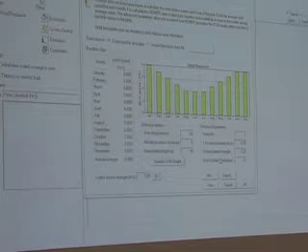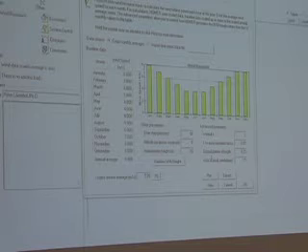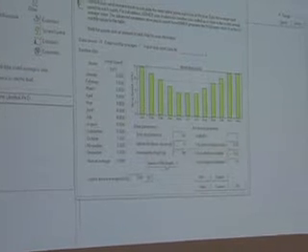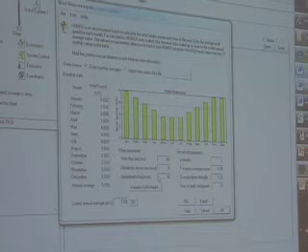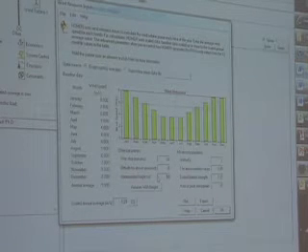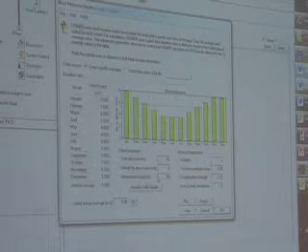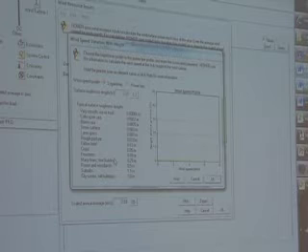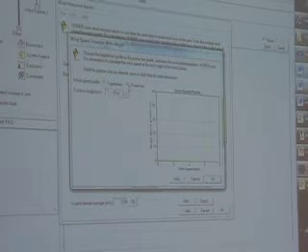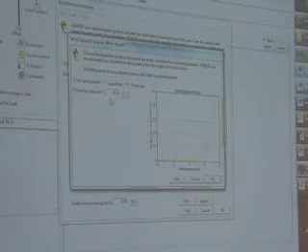Somebody asked about adjusting for the wind turbine. There's 2 ways we adjust for the wind turbine, then we'll break. One is we do an adjustment for height above ground, right here. So we ask for the anemometer height here. The data that you're putting in is for the resource at that height. And then we increase it based upon shear calculations. You can either use a logarithmic shear calculation using these surface roughness values or you can do a power law. 0.14 is the 1/7 power law, which is a common default.